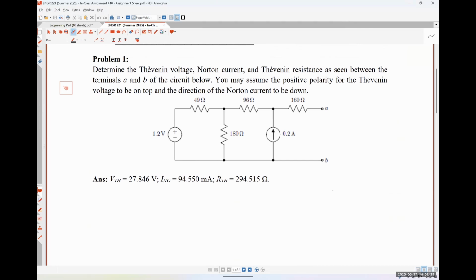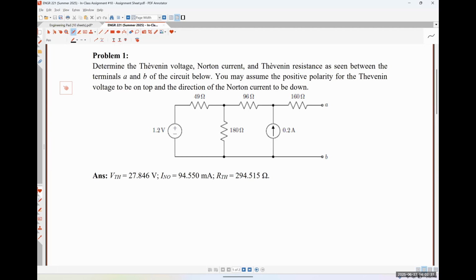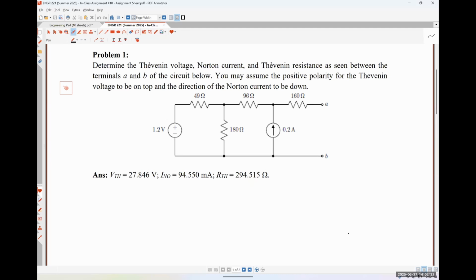Okay. So we'll take a look at this guy really quickly, and that'll serve as a review for what we're about to do today anyway, since we're just going to be looking at Thevenin and Norton equivalent circuits again. But this time we're going to include what happens when dependent sources are around. So if we're specifically trying to find the Thevenin voltage in this system, that is going to be the voltage present across the open circuited terminals, which would be this voltage right here.